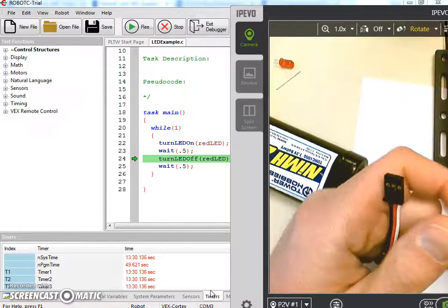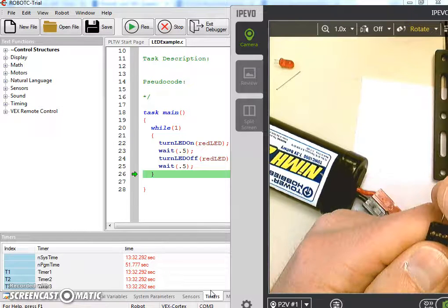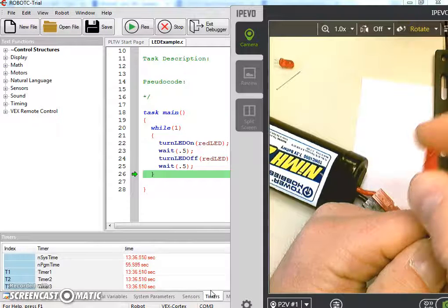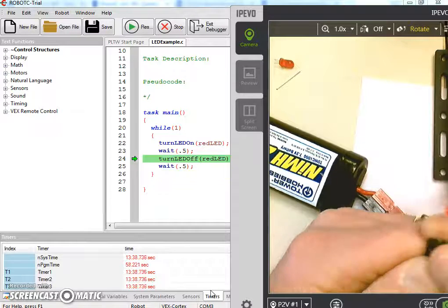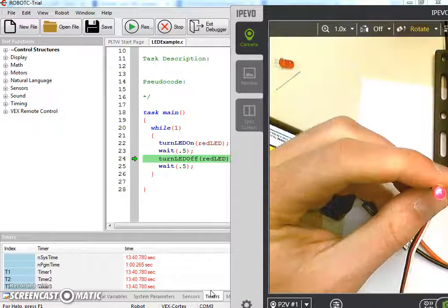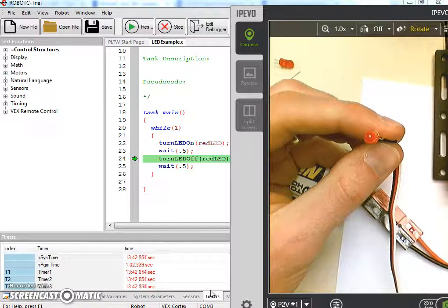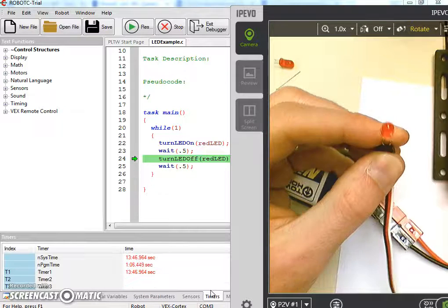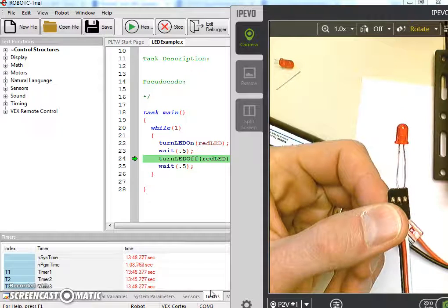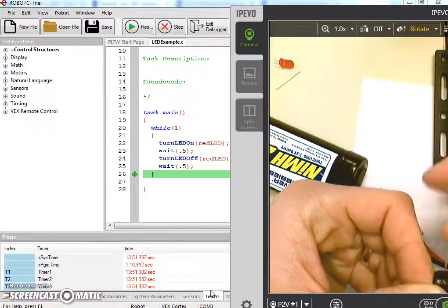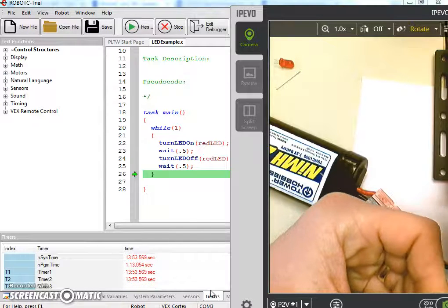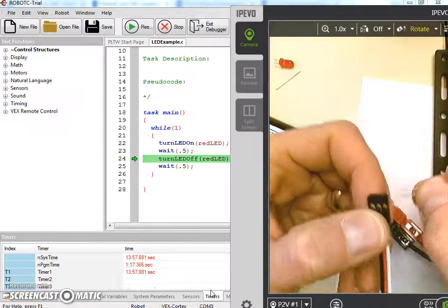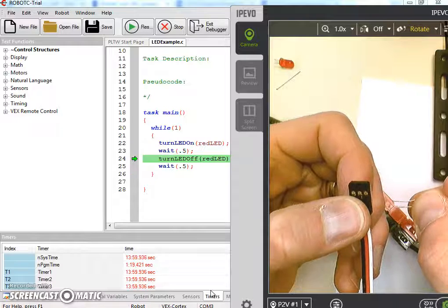Usually what I do is I trim off these leads, because if you take this out and I plug this in, again, I'm looking for the flag side to go in the signal, so the same thing. And I can actually just plug these into this hole here, and you can see that it's blinking as well. So it just plugs in, and it does what the other one was doing. But if you notice, I've got way too much lead sticking out there. So usually what I do is I clip so that there's only about 3/8 of an inch or so remaining.